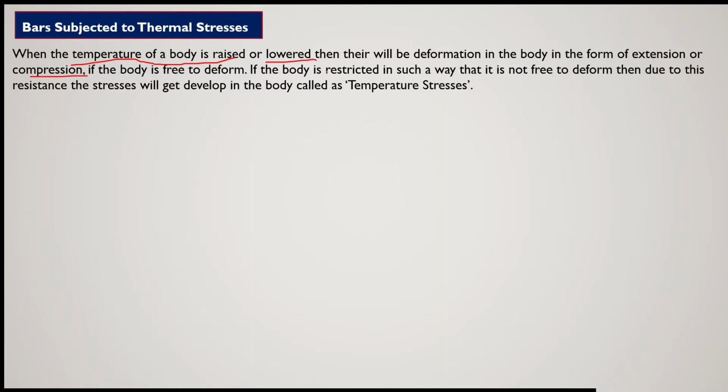Now, if the body is restricted in such a way that it is not free to deform, that means if there is a steel member restricted from both sides along its longitudinal axis, just like fixed supports, then those supports will resist any type of extension or compression of the member.